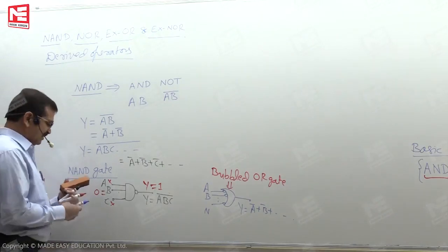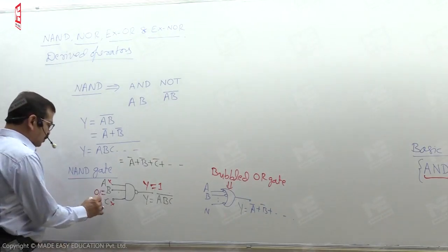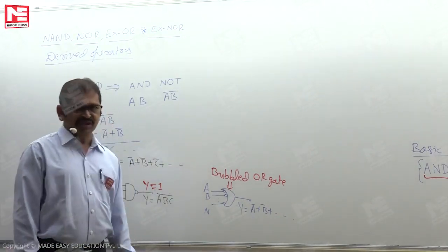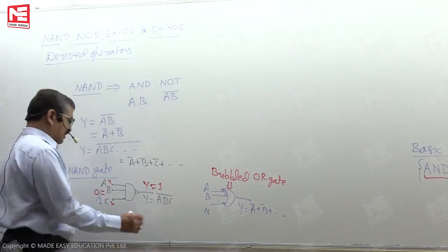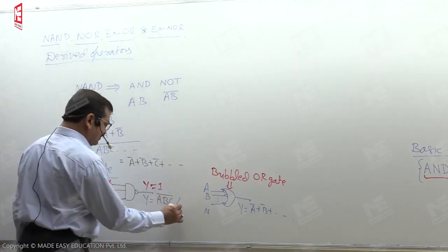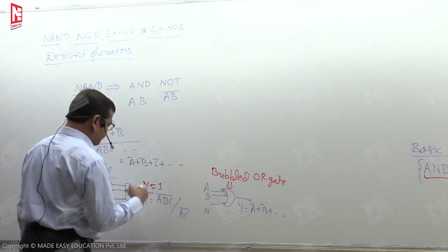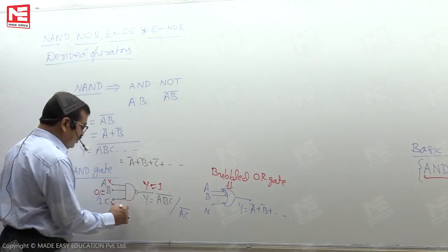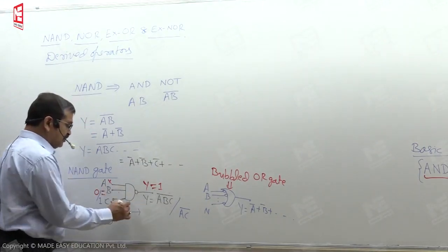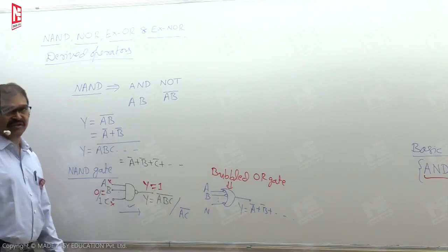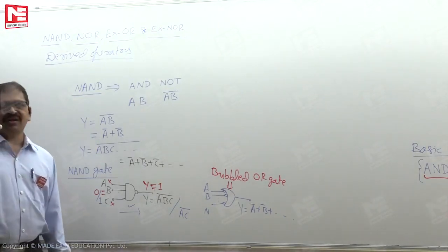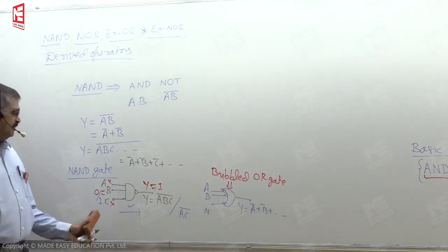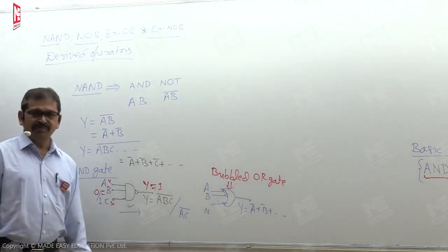Similarly, if B variable is given as 1, while referring to the truth table, it is possible to speak the output will be AC complement. It means if B variable is 1, the output depends upon A and C values. It means A and C variables are allowed to pass through this gate. Such state of the logic gate we are speaking as enable state. Such input we are giving a name as the enable input.